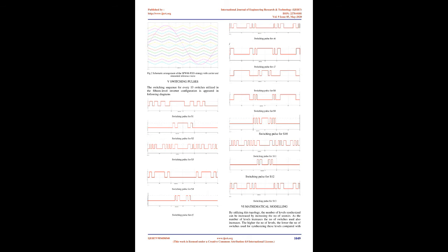Advantages of multi-carrier PWM techniques: 1. Easily extensible to a high number of levels. 2. Easy to execute. 3. To distribute the switching signals accurately so as to limit the switching losses. 4. To compensate unbalanced DC sources. Out of these SPWM techniques, we have used the phase opposition and disposition technique in the switching scheme to trigger the gate circuit, as it achieves the lowest line-to-line harmonic voltage distortion.